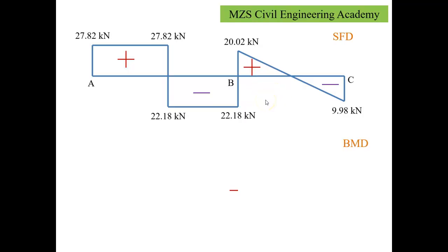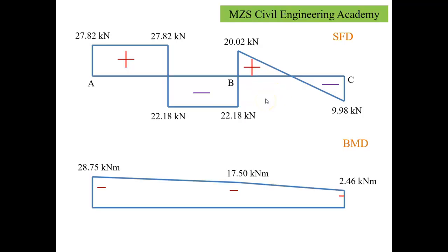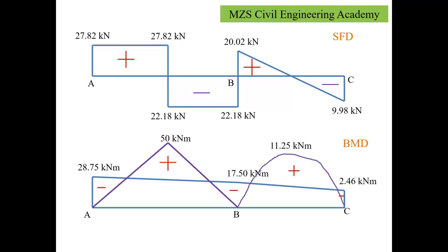Now similarly, I can have the bending moment distribution over the span. The fixed end bending moment has been shown here, which we have derived from the three moment theorem. Now to get the net bending moment across the beam, I have to overlap it with the free bending moment of this particular beam. So we'll get the envelope with overlap of positive and negative axes, and the area under this envelope is called the net bending moment diagram. Likewise, we will be able to solve the numericals with the help of the TMT method.